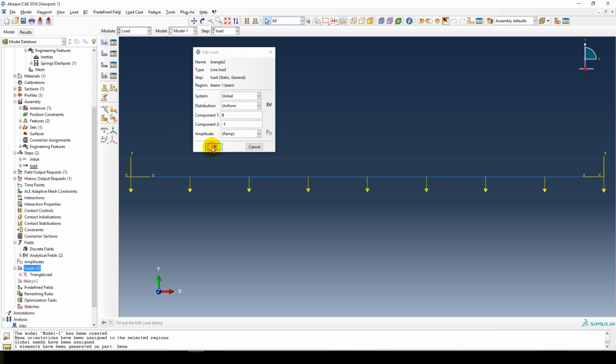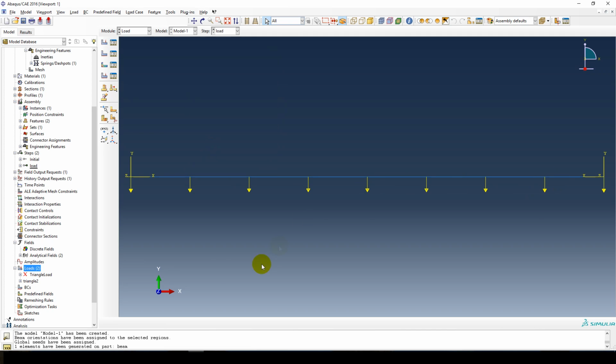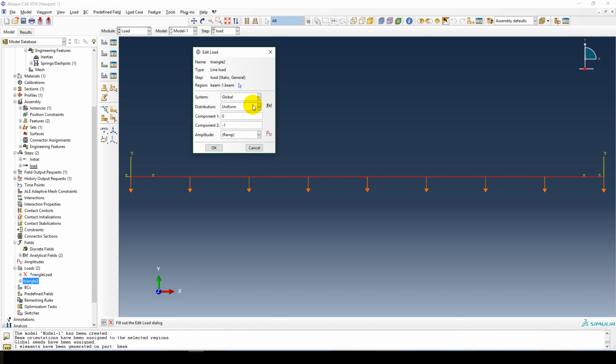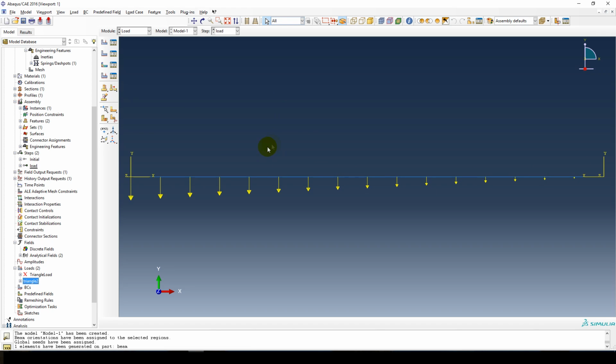We say OK. And that did not work for some reason. Let's say edit. Oh, because I created my field but didn't select my lineload 2's field. So let's try this again. And there we go. Sorry. So once you create something, you should select it. Otherwise, you run into trouble. So this is two equivalent loads, just different ways of creating them.